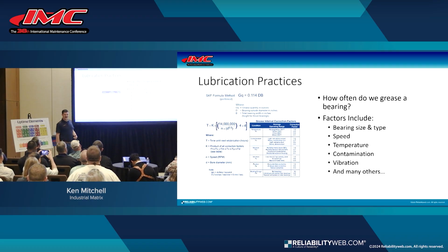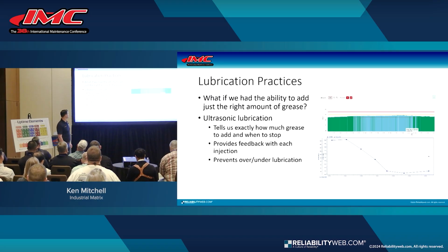However, there's a lot of factors that affect how much grease goes into a bearing. So temperature, contamination, moisture, vibration, position, bearing design. There's a few more that probably aren't present here. So we can look at a calculator, we can look at the bearing, the OEM, but it still has us questioning how much grease do we put in a bearing? What is the optimal zone to lubricate that bearing so that we're cooling it and we're giving it enough of a frictional modifier that it doesn't act up on us?